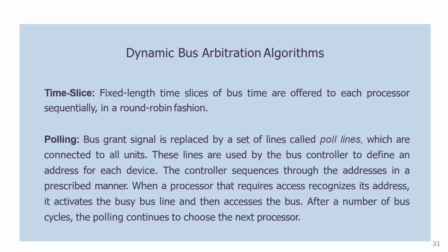The dynamic bus arbitration algorithms. The time slice means that a fixed length time slice of the bus time is offered to each processor sequentially in round robin fashion. So this time slice can also be thought of as round robin, which you should have studied in operating systems.